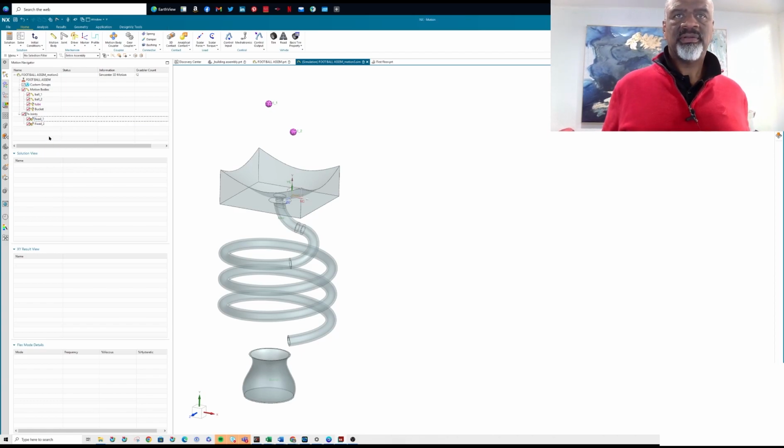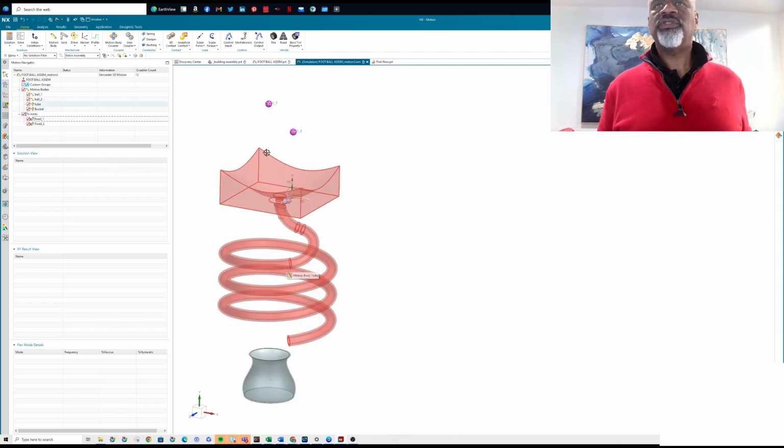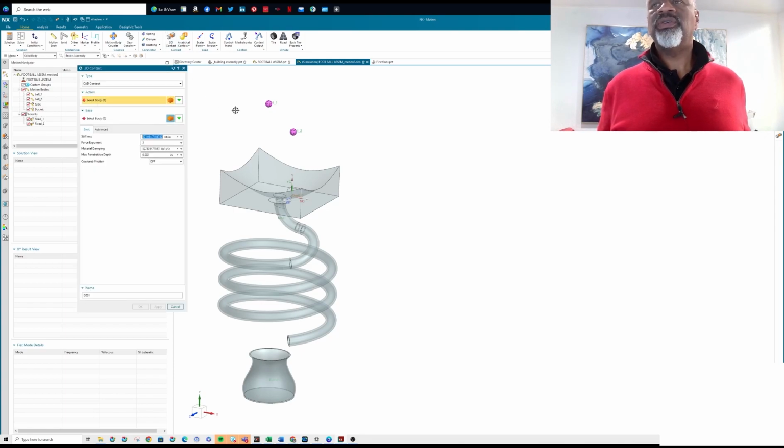And we're going to do a rename on this one, because it's really important to keep track of these things. Okay, so now that we have two of the essential joints that we want, the next thing we're going to do is make a contact, a 3D contact. And what we're trying to do here is make sure that this will contact that when it falls in.